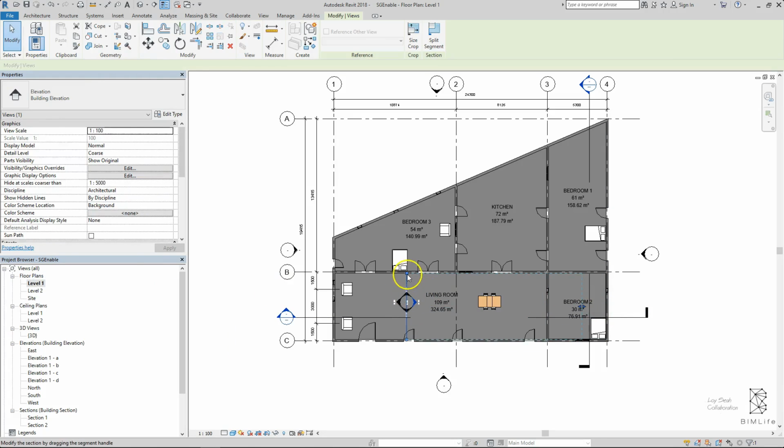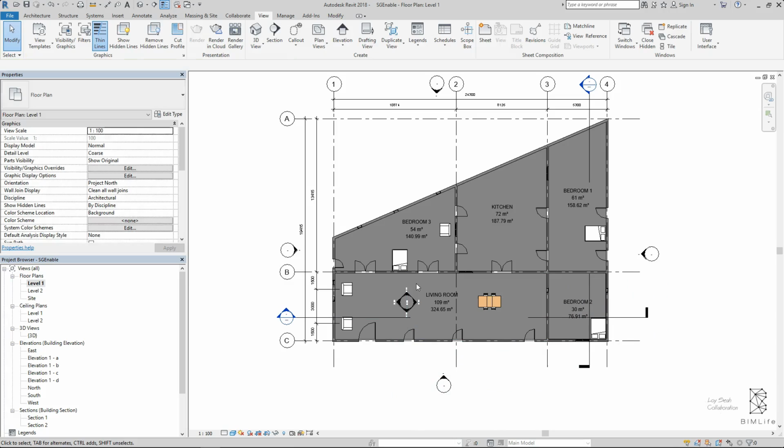You can see the extents of your elevation by simply clicking on the elevation once. This is the boundary, for which Revit provides you a drag arrow. You can view outside the room using this circle. So we have finished creating elevations and sections in our model, as well as accessing them as and when we want to open the view.